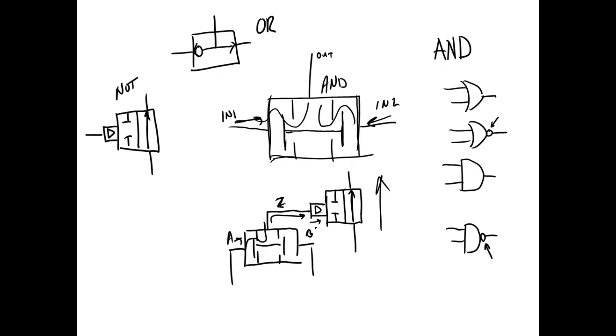You understand? On the NOR, if either input is true, and I send the output of that shuttle valve into a what? Into a NOT, which is a normally open valve. If I send it into the NOT, then that means if both my inputs are false, then my output's going to be true. If either input is true, the output's going to be false. Now, when we say true here, we're talking about pressure. So pressure is true, no pressure is false, right? And that's the easiest way to explain logic. And we can do that in PLCs. We can do that when we use truths and false.